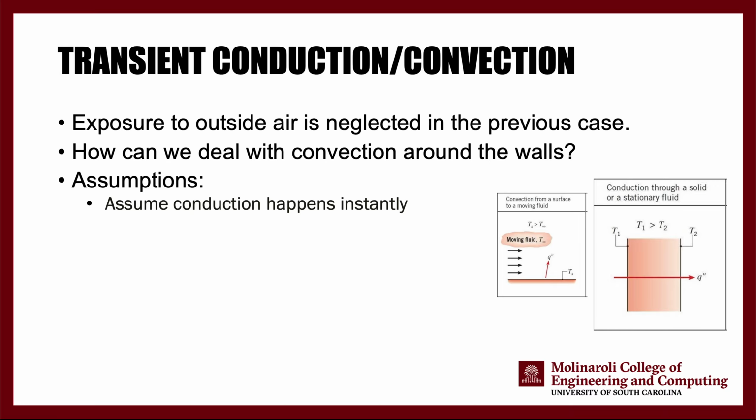Okay. The assumption we are making here is that the conduction inside that copper block is happening instantly. So the change of temperature of the block only depends on the time that has passed, the transient part of it, and the convection with the outside air.